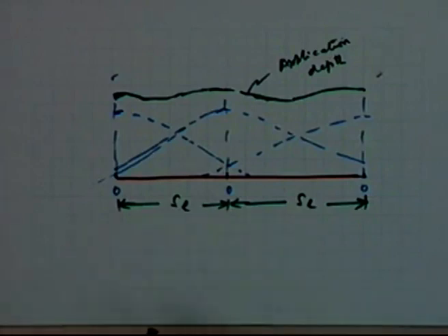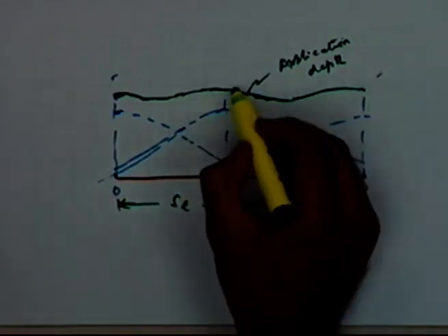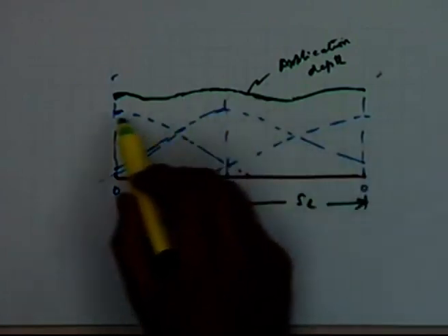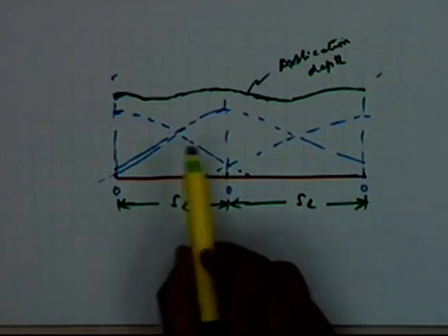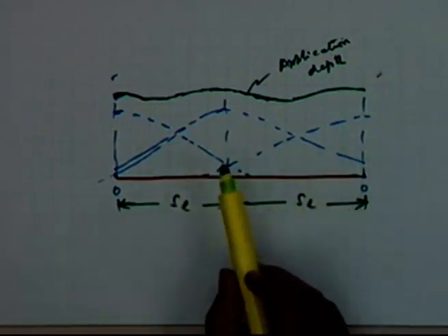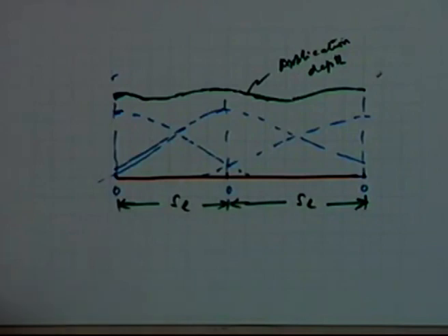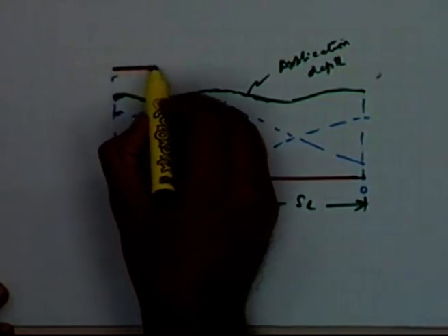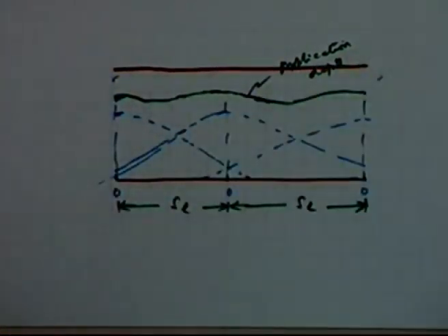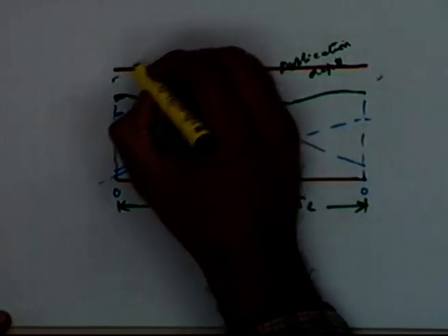These two levels of overlaps will decide the ultimate uniformity coefficient, or the overall distribution pattern. And you will also understand at this stage that it is very difficult to get a distribution pattern which is very uniform, almost a straight line. This is very difficult to achieve.